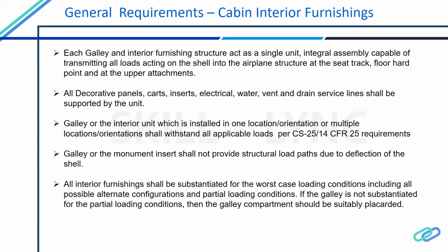And that's one of the special considerations that we have to have when we are analyzing a particular galley or a monument which has a baby bassinet. So if you get a chance to analyze that, you need to analyze for the ultimate load conditions without the baby bassinet, and the in-flight load conditions with the baby bassinet. So that's what I've told.